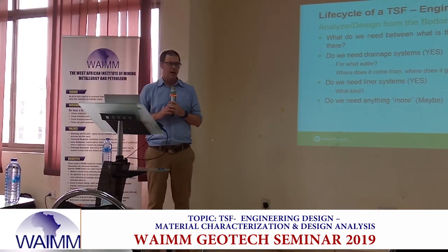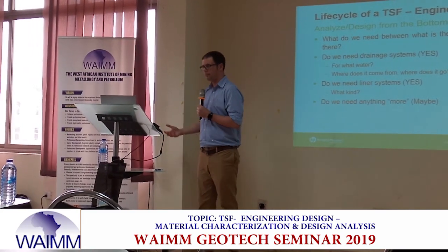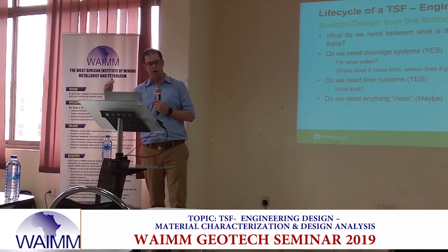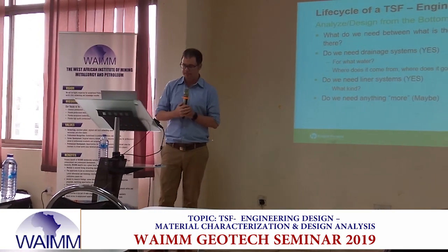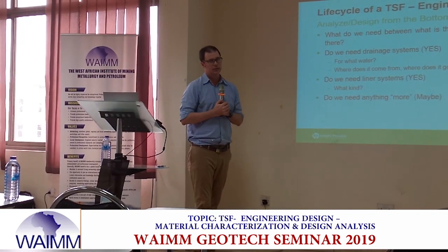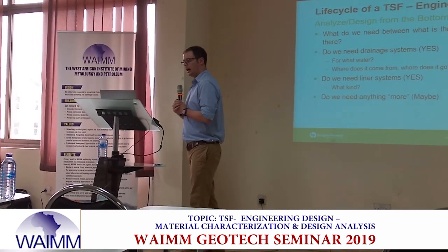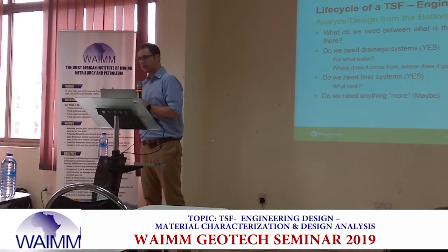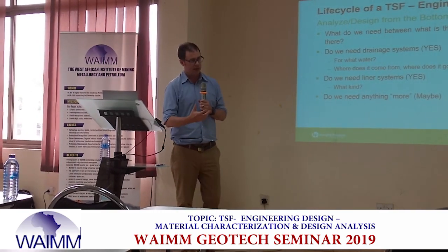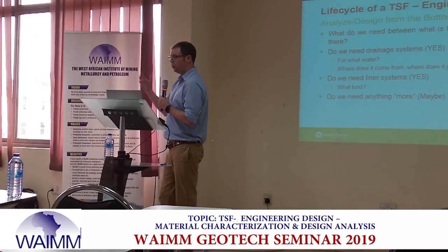So, when we're analyzing and designing, we want to do it in the same way that we would build something, from the bottom up. We talked about foundation investigation, then we talked about fill material. Same thing with our analyses. We should design from the bottom up. So, what's between us and what we want to protect? That's going to be our hydraulic barrier, our drainage systems. Do we need anything beyond a standard hydraulic barrier, a compacted soil liner? Do we need a geosynthetic? Do we need an underdrain system or a groundwater collection system?